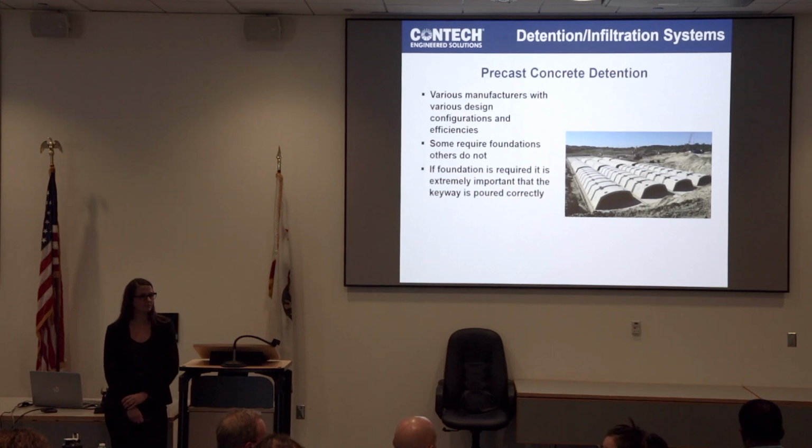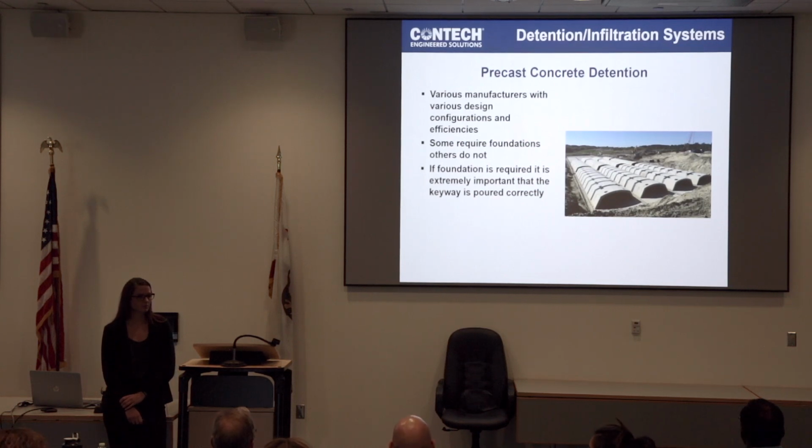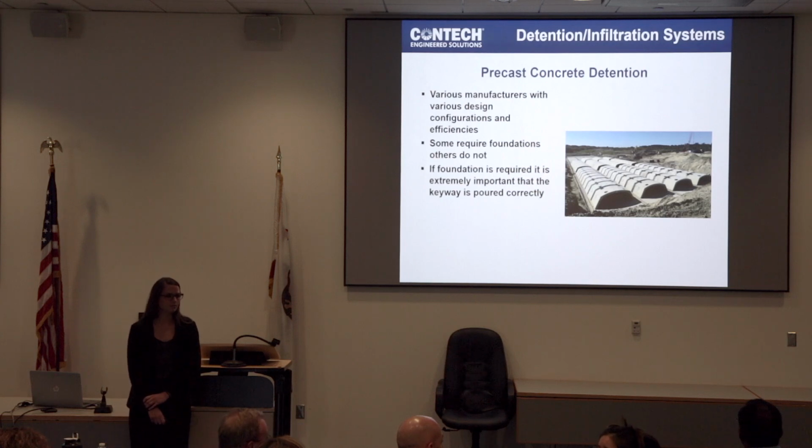Since concrete is pretty heavy, most of the time it's going to require some sort of crane to set it. Some systems, if they're small enough, you can use a mini excavator to set them. So I think it's really important to understand this in the beginning when you are designing, to understand that you might need some heavy construction and access.